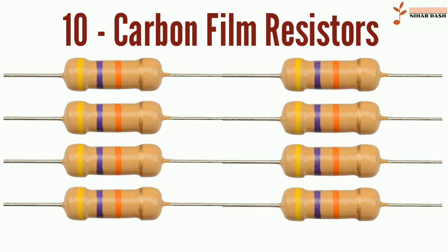Carbon film resistors feature a power rating range of 0.125 watts to 5 watts at 70 degrees centigrade. Resistances available range from 1 ohm to 10 megohm. The carbon film resistor has an operating temperature range of minus 55 degrees centigrade to 155 degrees centigrade. It has a 200 to 600 volts maximum working voltage range. Special carbon film resistors are used in applications requiring high pulse stability.